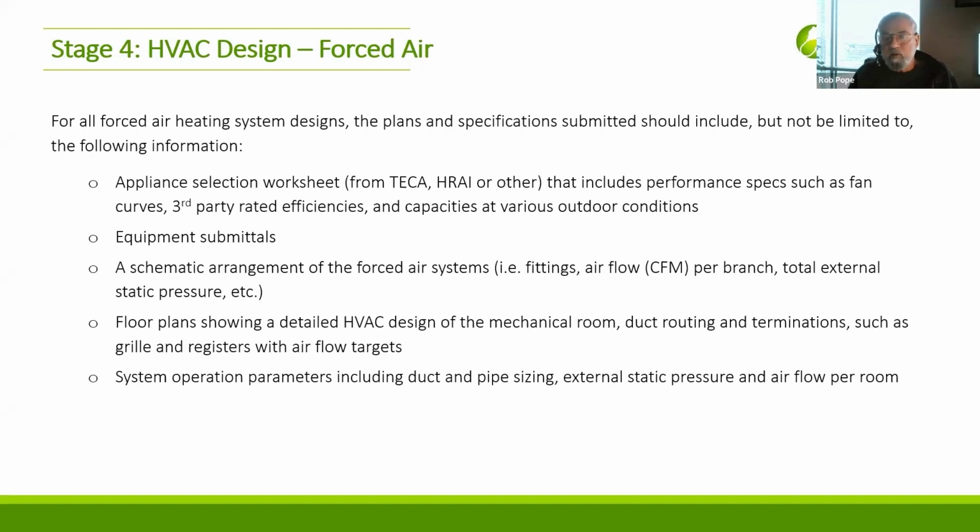Fittings, airflow, CFM per branch, all that kind of stuff that you need to put on the document that is called your design, showing how you arrived at those numbers. And of course, you want to draw it out in a way that it's clear where all of the pipe and the duct is going, and making sure it doesn't go through beams and that kind of stuff.